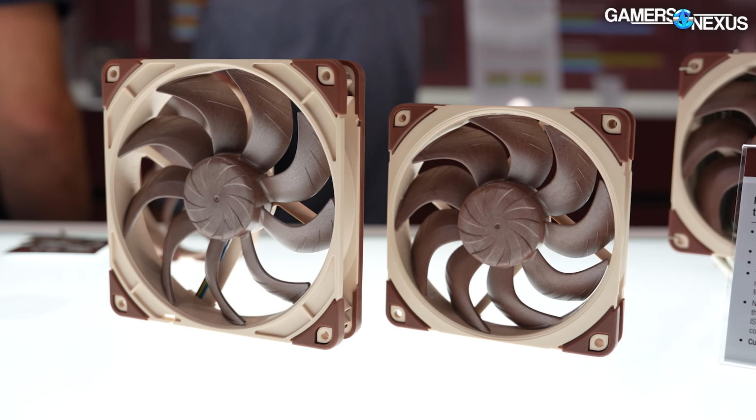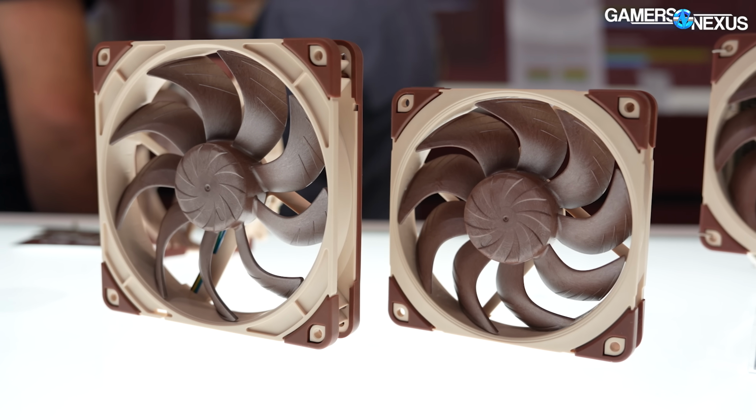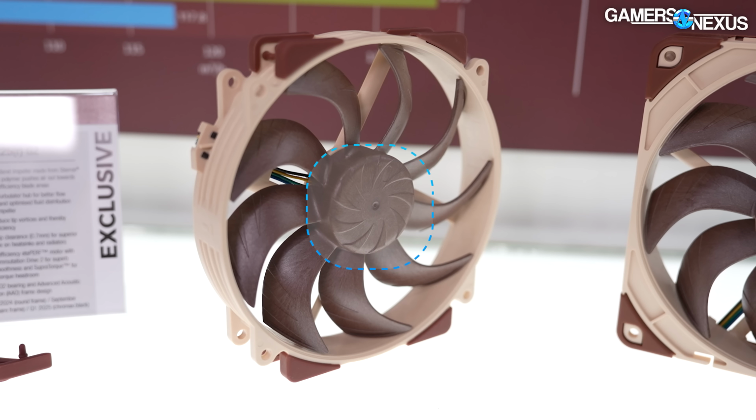And with these, we utilize the phenomenon that turbulent flow better attaches to surfaces than laminar flow. You have the same phenomenon with a golf ball where the dimples reduce drag because there's a turbulent boundary layer forming across the golf ball. So there are examples where turbulence is beneficial. So in our case, with the G2 fan, we don't have an example here, but you can surely find a B-roll for it. This enables us to have better flow attachment at the hub region, where generally things are very difficult due to the general low speeds of the fan blades.